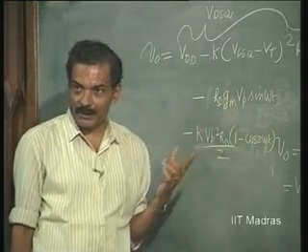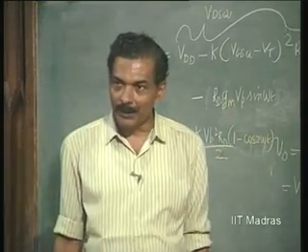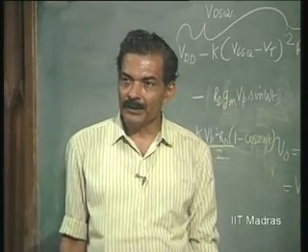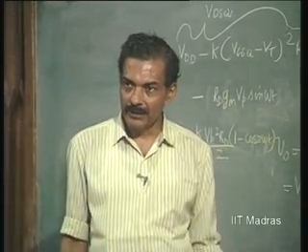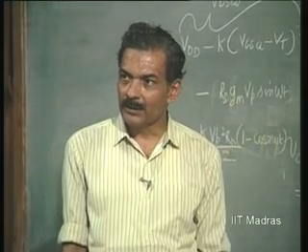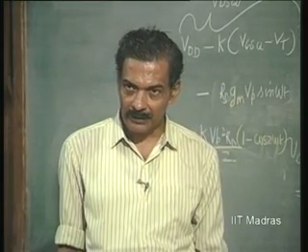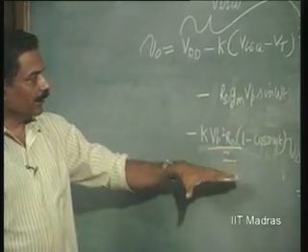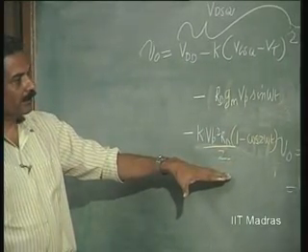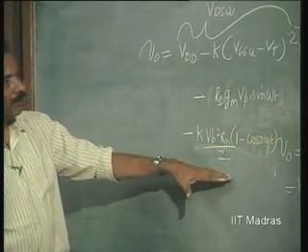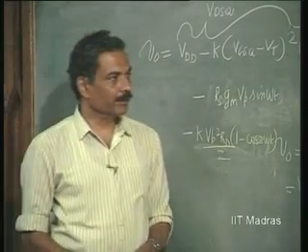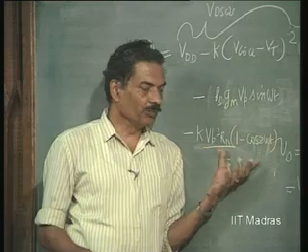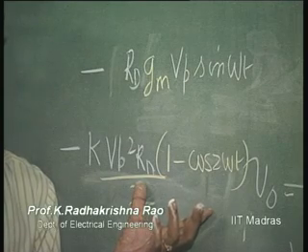The distortion obviously depends upon Vp. So, it will tell you the magnitude of Vp that should be constrained in order to keep the distortion at a value less than 1%. So, this part of the design is important in restricting the inputs to specific values.